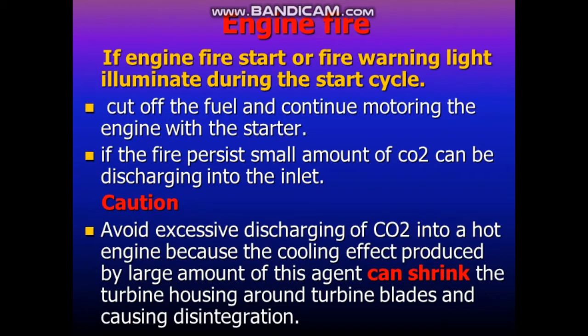If the fire persists, a small amount of CO2 can be discharged into the inlet, and you have to take this caution: avoid excessive discharging of CO2 into a hot engine, because the cooling effect produced by a large amount of this agent can shrink the turbine housing around the turbine blades and cause disintegration.